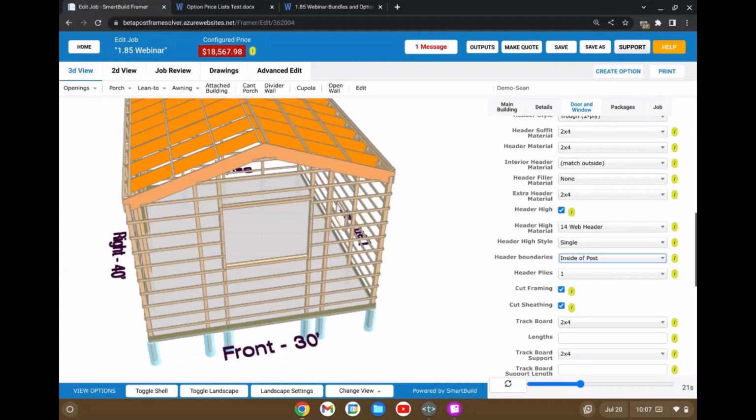Right, you need something to support the girts, and it's the same issue above it, right? That's right. If you have a 30-foot wide door in the side of your building, and you've got 10 feet above the door to the top of the building, you've got to have something. You've got to have some posts in there to support that. Okay.